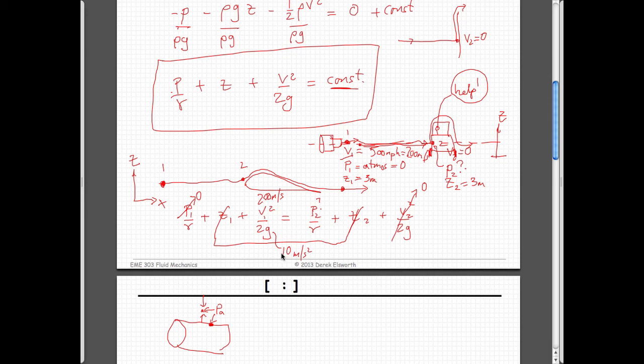If you go inside here, then the fluid acting radially into this is also atmospheric. And since we know that the fluid pressure acts the same in all orthogonal directions at a point, albeit for a static fluid, then the pressure here is equal to atmospheric, and we're taking atmospheric as equal to 0 gauge.